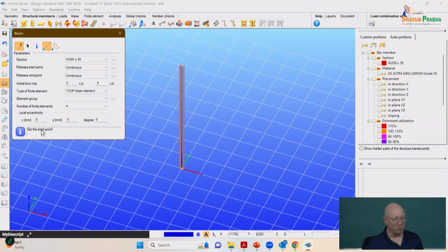So for the beam, it wants us to do a start and an end point, and any point we've already selected, if we wanted to put it into the middle of the beam, it has some control points. The column, you have some control points along the column you can see highlighted there. That's related to the N over here in the lower right, N of 4. Here, I could set that to something else and I would see more points I could snap to along the column length to insert things.